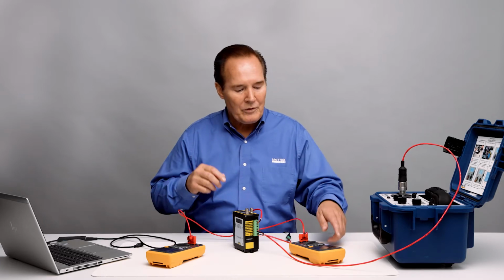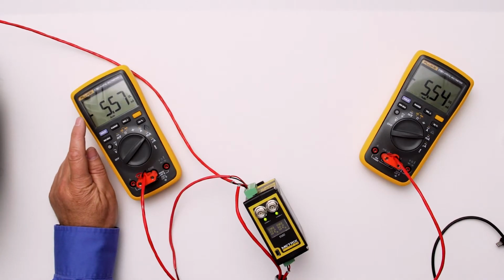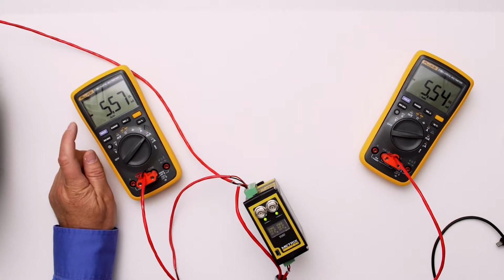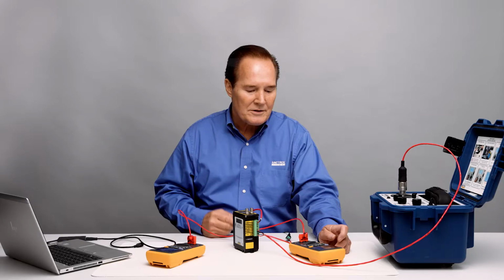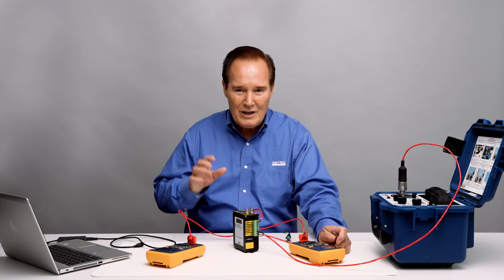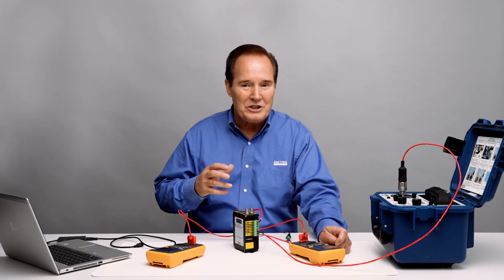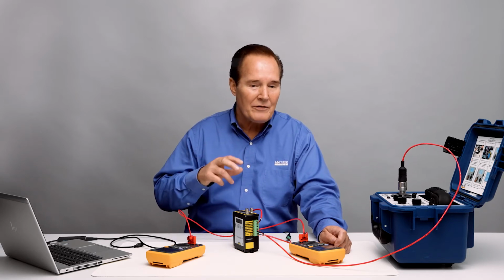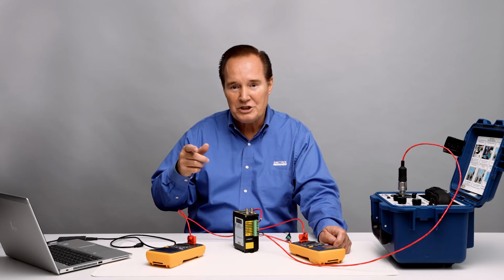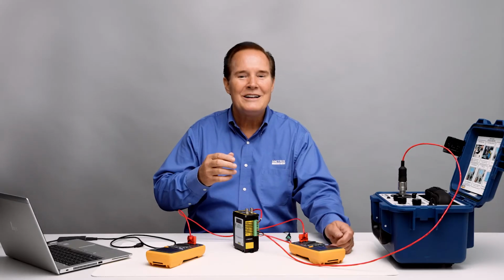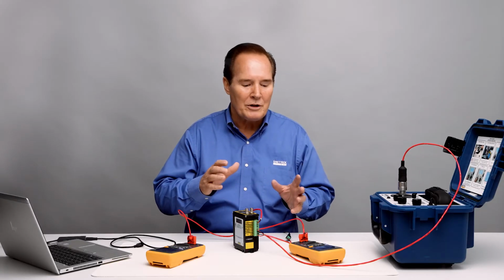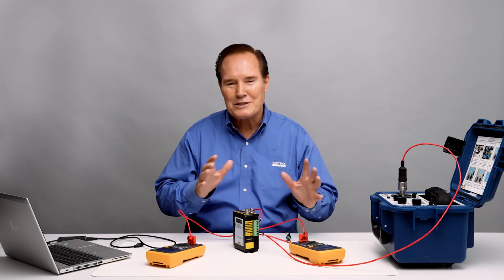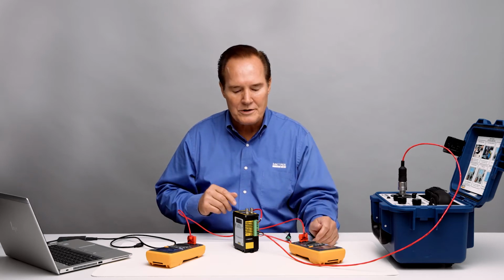So when this is vibrating at 1G at 20 Hertz, we'll see 5.6 milliamps approximately. Because I'm at 1G, it's 100 millivolts per G. The scale factor is 0 to 10 Gs. So 16 milliamps divided by 10 is 1.6 milliamps, plus 4 gives you that 5.6 milliamps. That's pretty close, and it has to be within 5%, so that's plenty close.